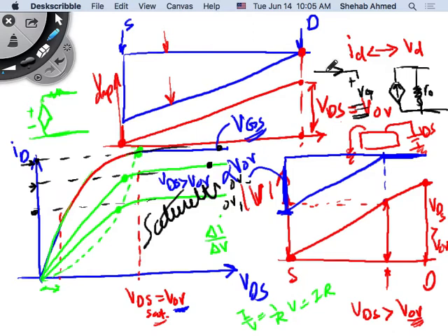So I have an infinite input impedance because I am not drawing any current at the input, and I'm not losing any voltage when my load changes because I have an infinite output impedance in parallel to the current source. That's why the impedance is infinite, because we don't want any current, we just want ID to be the one that affects things. I want ID to be controlled by the gate voltage, right? Which means I want this current that's going to flow out of my device to be controlled by my input parameter. That's nice. Then I can put in a small voltage and control a huge value of current, right? So that's the beauty of the model.